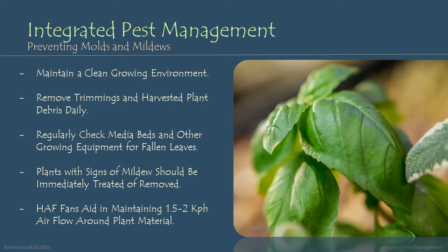As a side note, because molds and mildews thrive in high humidity environments, if you're using an evaporative cooler or a water wall to maintain lower temperatures in your growing environment, you are drastically increasing the relative humidity of your growing environment by doing that. And while I am a huge fan of utilizing evaporative coolers in growing environments, if you're using one or a swamp cooler to maintain the temperature of your greenhouse, you are increasing your risk and exposure to mildew and mold developments on your crops. So if you're using an evaporative cooler, be extra diligent about checking regularly for molds and mildews on your plant surfaces.